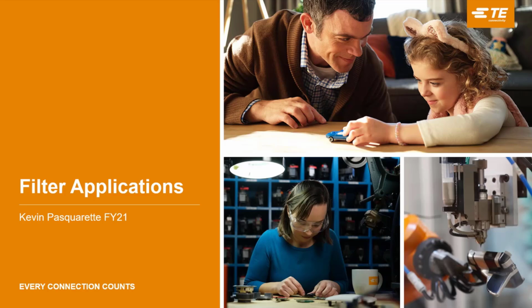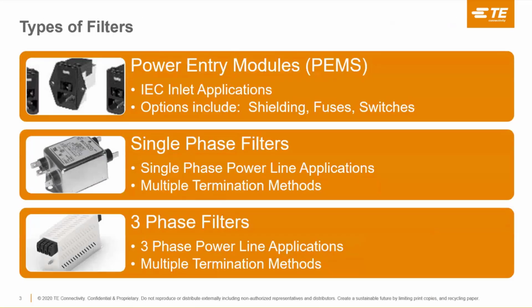For the first hour of this session, we are going to go through filters and filter applications. So, types of filters. We have power entry modules, which we will call PEMs, and basically these are just IEC inlet applications. It has multiple options, including shielding, fuses, and switches. We also have single phase filters for single phase power line applications, and these have multiple termination methods, could be fast-on tabs, nut and bolt, and terminal blocks. And then we also have three-phase filters for three-phase power line applications, and again, they have the same multiple termination methods.